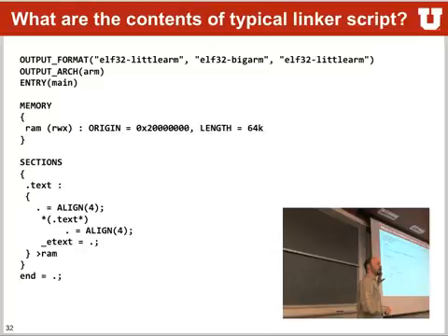We will look at more complicated ones later on and also in lab, where you can put stuff not just into RAM, but also into ROM. And usually into ROM, you only store stuff that's constant, so either executable or readable, but usually not modifiable, because modifying ROM is either impossible to do if it's burnt in, or if it's flash memory, you have to use specific functions to actually go and modify your flash. So usually ROM is only read and executable, while RAM is read, write, and executable.